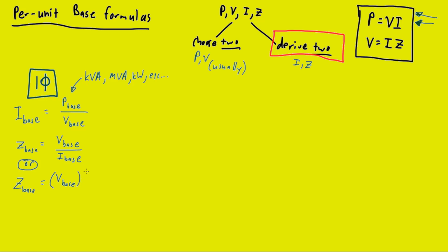And instead of using just the V equals IZ formula, you would use sort of a combination of those two very simple formulas to come up with this third overall formula at the bottom here. This third formula of impedance equals voltage squared over power should be sort of in your bag of tricks of formulas, if you will. It's another very simple formula. And we'll just go through the algebraic spelling out of this formula to demonstrate its roots in our two very fundamental formulas at the top.